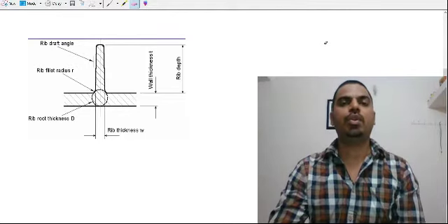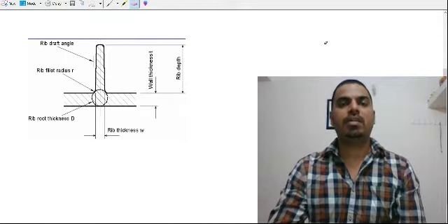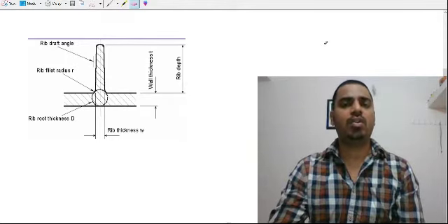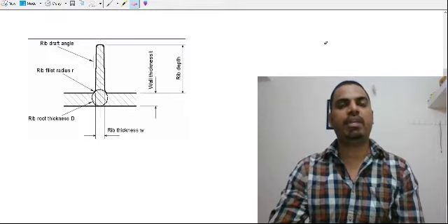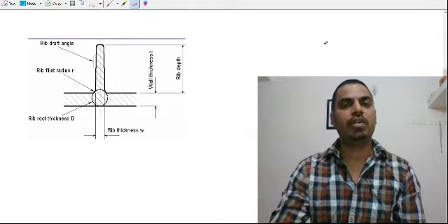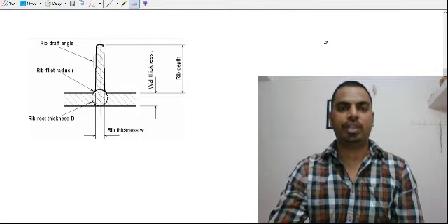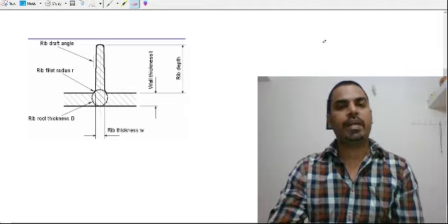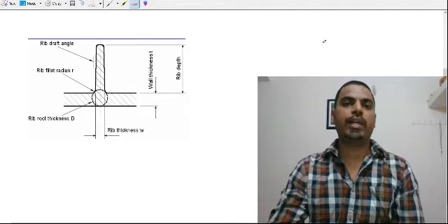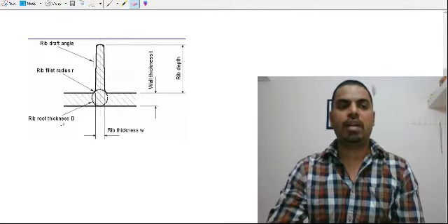Ribs are basically used to provide strength to a given part. Suppose you want to increase the strength of a given plastic part. We can also go for increasing the wall thickness, but it will again result in increased material cost, as well as the weight of the plastic part. So instead of increasing the wall thickness, we can provide a sufficient amount of ribs in that location. If we provide a rib, then where the rib joins the wall, there will be an increase in thickness. So let's understand this phenomenon by this graphical representation.